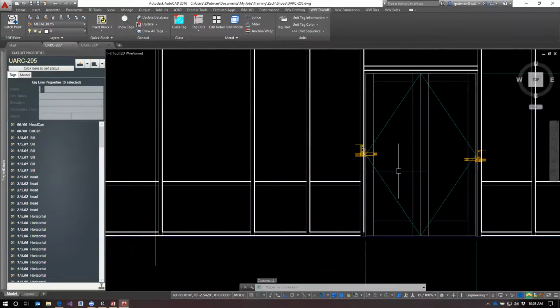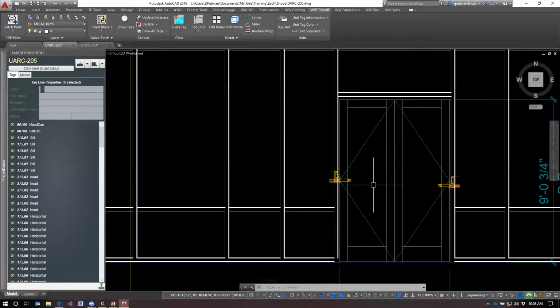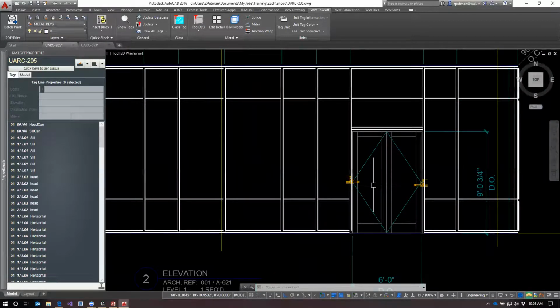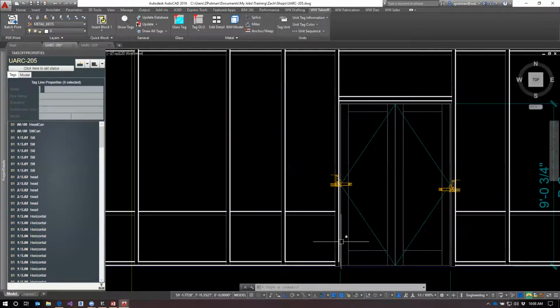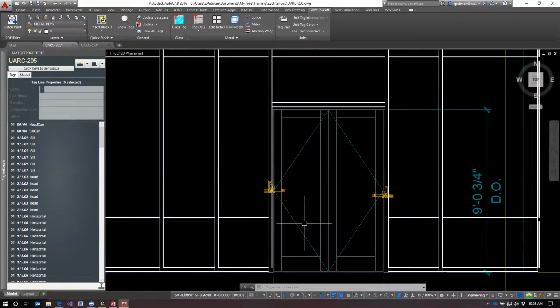So is that the preferred method? You want to see a separate tagline as opposed to doing a fixed length and adjusting top and bottom for that channel? Oh, heck yeah. Because when you make it a fixed length part on this vert, now it only works at one door size, and you'll have to make another copy of it to do another door size. It just limits your flexibility.